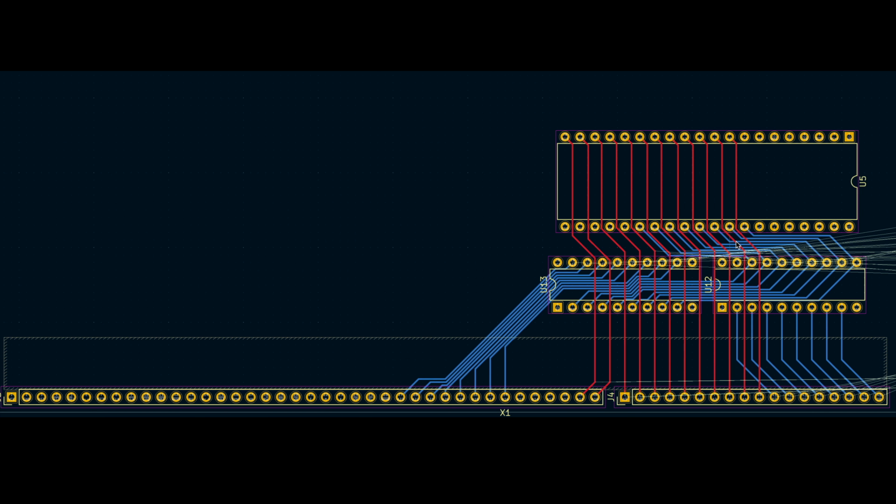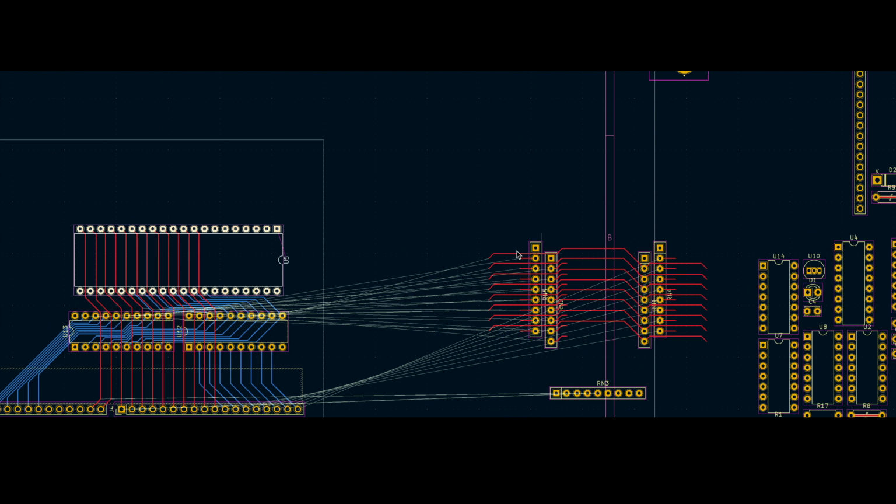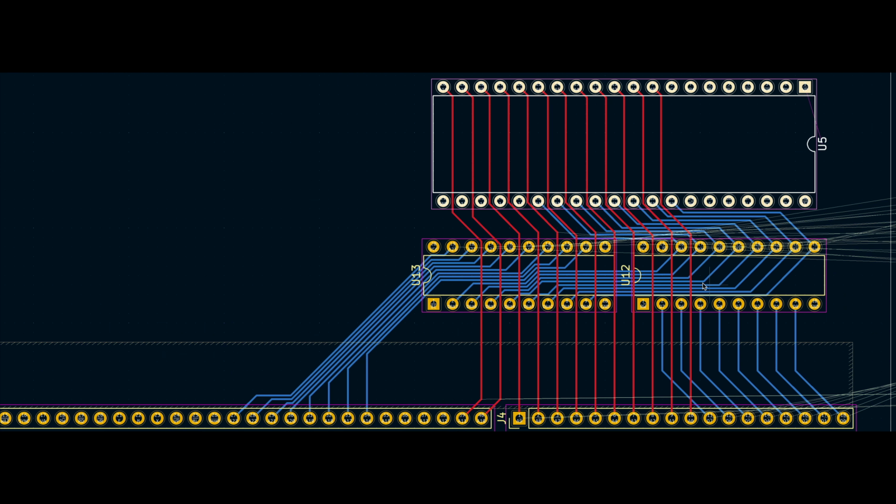This is another setup that I'm working with at the moment, with the CPU the wrong way around. It kind of makes it possible to route everything in a quite compact way, but I haven't put any of the pull ups and pull downs. One thing I'm noticing is that the data bus and the bank address all come from the multiplexed bus here, and it would make sense to have them together.